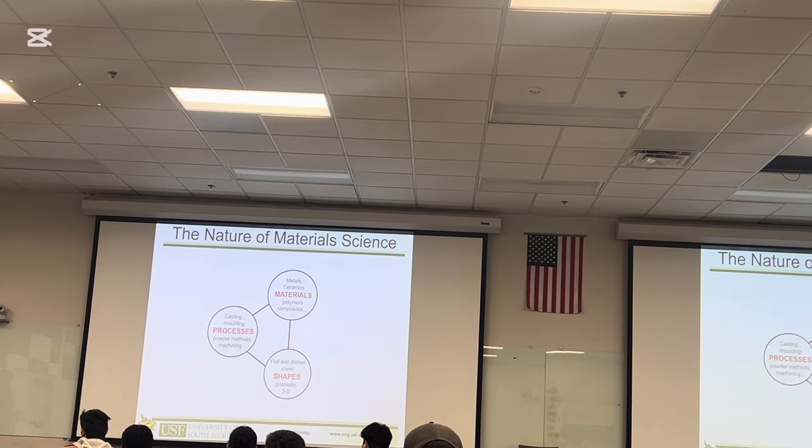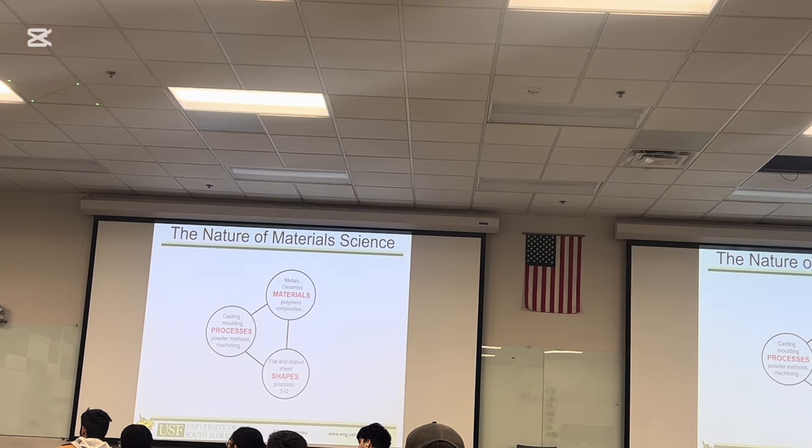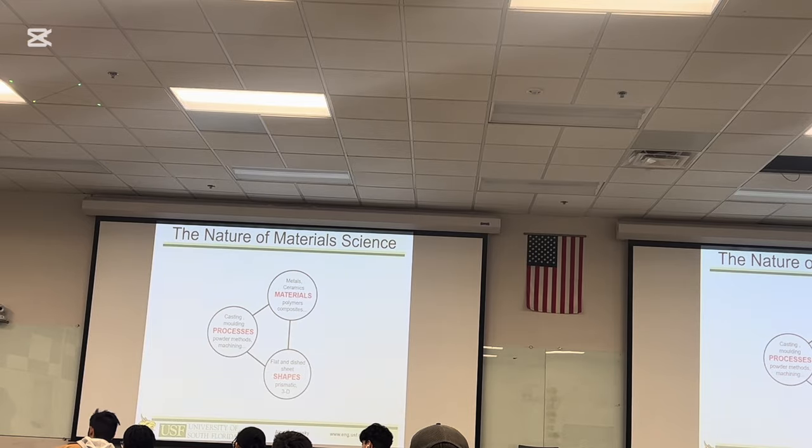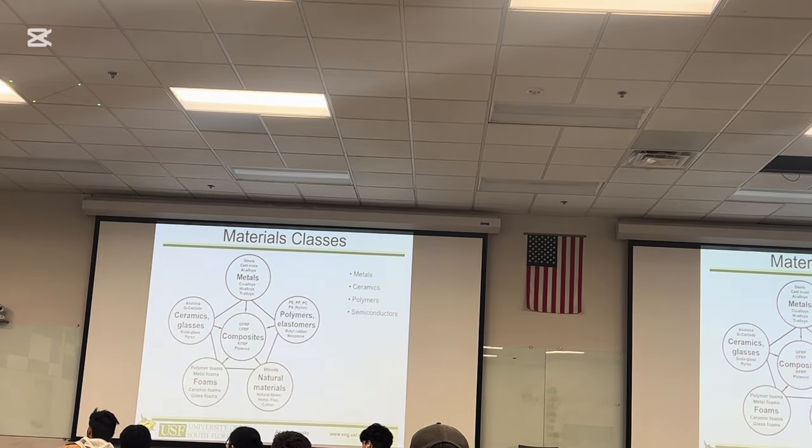He also introduces shapes, which has to do with mechanical performance. And shapes are important because you can see, somebody asked me about the airplane. Okay, this is the wing of an airplane. Can this piece of paper support its weight? No. Okay, what about now? Barely. A little better. What about now? Now, at some point, this becomes a weapon, because it is a weapon. So there's only one kind of loading configuration where it doesn't matter. Obviously, like for bending, even for compression, it matters. But for tension, this wouldn't matter, because I can pull on this or I can pull on the whole thing. It makes no difference. Okay? So depending on how the material is loaded, then you have to worry about the performance. And you can improve the performance by like a factor of 100.